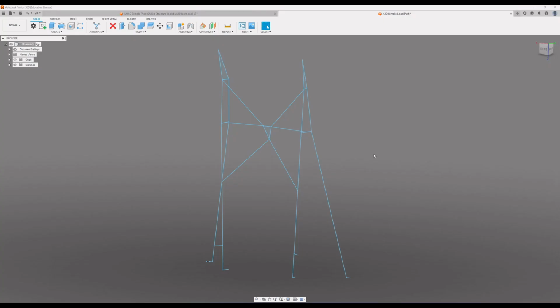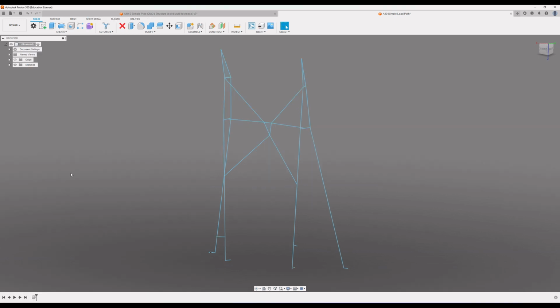So ideally you want to bring this DXF that you saved back into a CAD program. So here we're using Fusion 360. An important thing to note if you are using Fusion 360 is you'll want to turn on your design history. And that way you're capturing that as you work. And that's just a nice cleaner workflow.